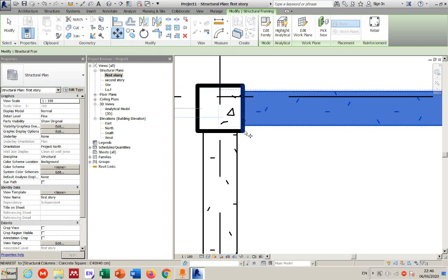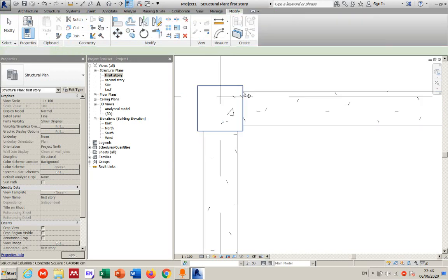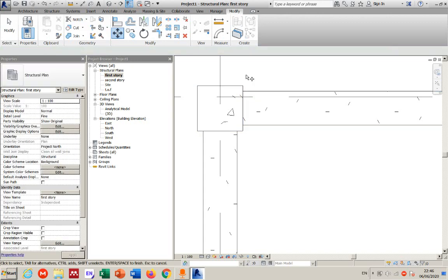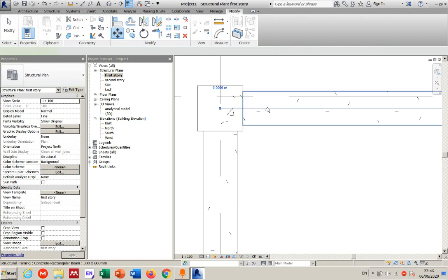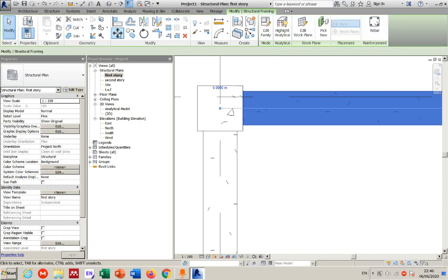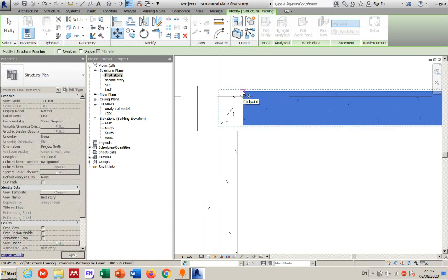Then I can use this point. If you don't want to see those lines as bold, you can just simply click on the thin lines. Then you can easily move. So first, the easy way to do it: if you press on move and select, you have to follow by an enter, then you can move the command. So the easier way to do these things is to first select the member, then when you click on move, it directly will ask you for a point, and then you're going to move that point here.